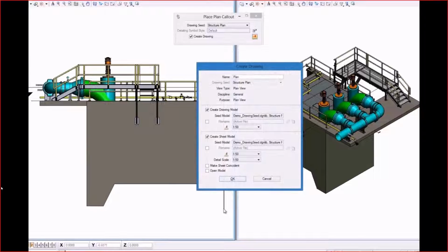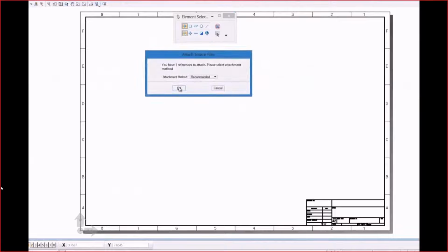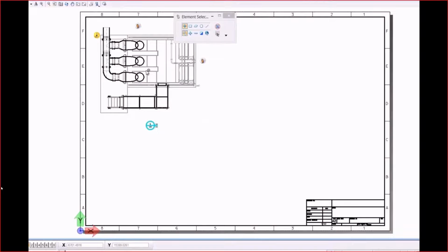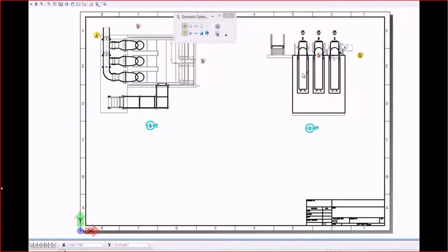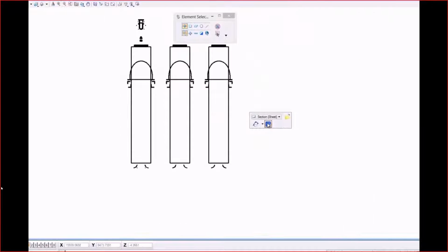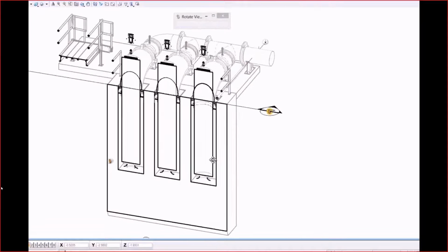With all the drawings created, just navigate to an empty sheet, for example, to drag and drop from the MicroStation Explorer all the drawings needed to create automatically, intuitively the final composition for your project. Then once you have your sheet ready, just using the bubble, you can quickly jump from the 2D drawing to the 3D model and check sections and model in the same view, for example.